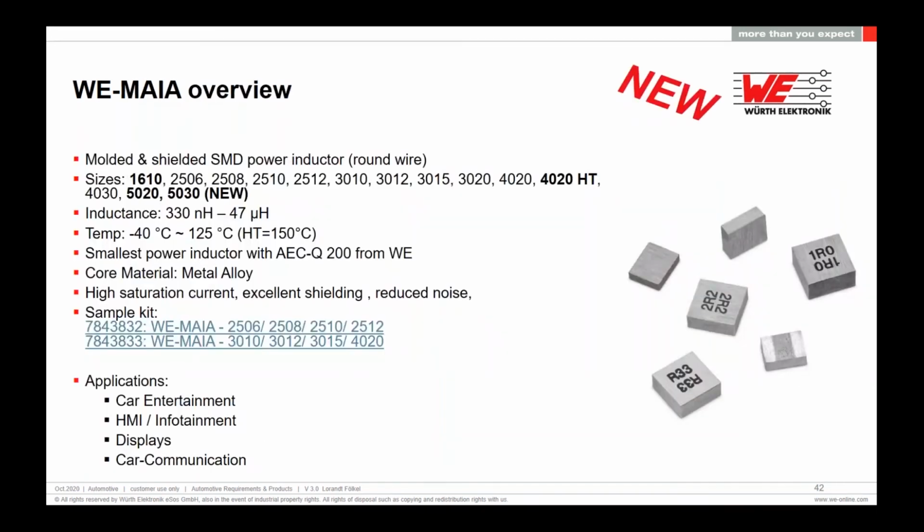The best shielded inductor in terms of no air gap on top or bottom, like the PD has, is the Maya. Maya is not a ferrite sintered material. This is a metal alloy, which we produce a little bit differently from the standard inductors. You can have even some of those in high temperature, 150 degrees Celsius.